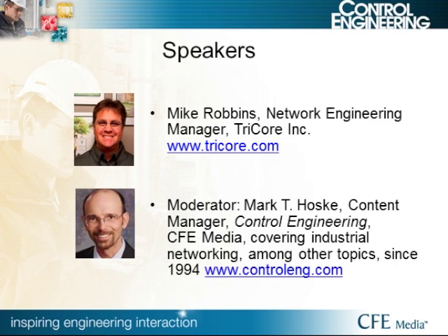So then, shielded versus unshielded cabling. If you have an environment that's high in EMI or RF, like aluminum plants, or if you're running cable within a control panel that has a lot of VFDs, or you're in an MCC, I recommend, and the TIA 1005 also recommends, using shielded copper cable.